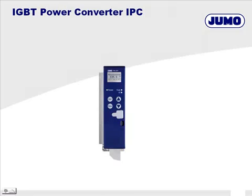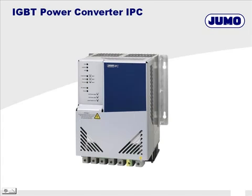A thyristor unit has a favorable cost-performance ratio and can be used for many applications. But both operating modes have disadvantages like EMC error potential and reactive power during phase angle control, or the low quality of control and the flicker effect during burst firing operation. Now we would like to show you the patented JUMO IGBT power converter IPC. This device allows for operation without the mentioned disadvantages.